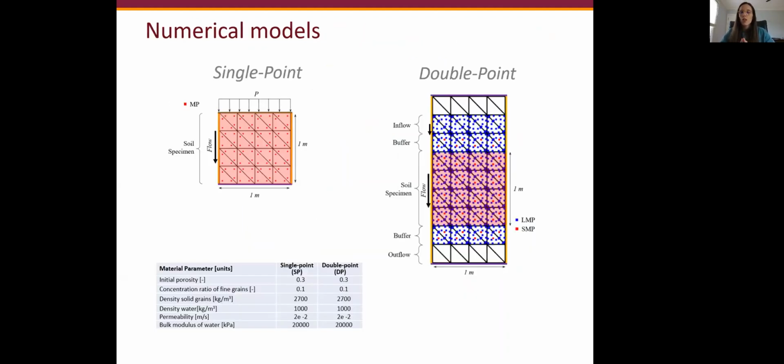In this presentation, we wanted just to validate this formulation using a theoretical problem with analytical solution. So we are considering what we call the suffusion process, which is internal erosion where the solid skeleton basically is not mobilized. So in these results, we assume that the solid material points are fixed or they don't accumulate any deformation.